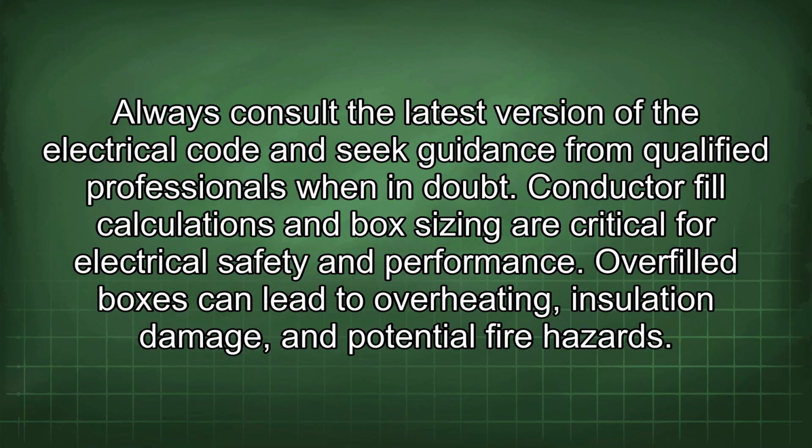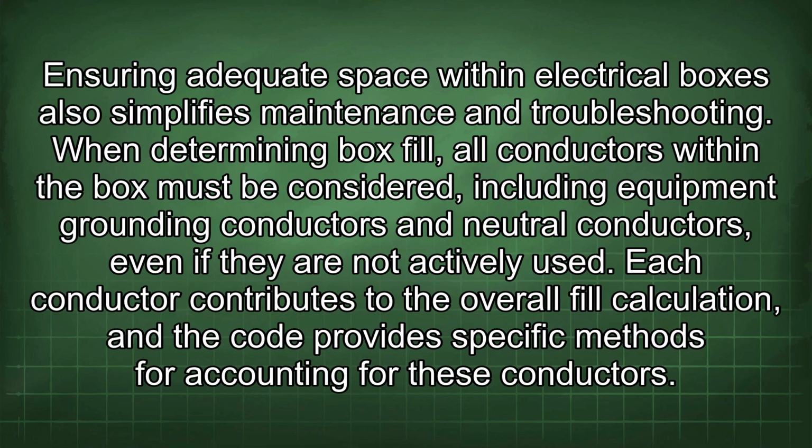Conductor fill calculations and box sizing are critical for electrical safety and performance. Overfilled boxes can lead to overheating, insulation damage, and potential fire hazards. Ensuring adequate space within electrical boxes also simplifies maintenance and troubleshooting.